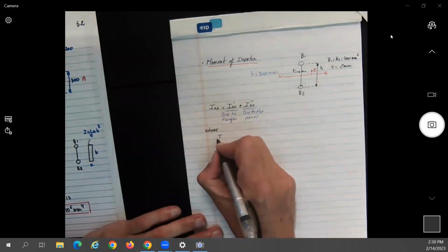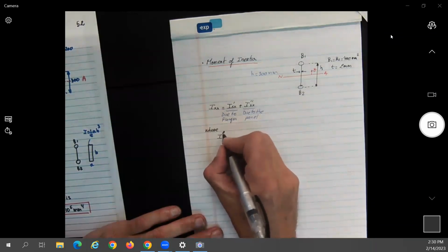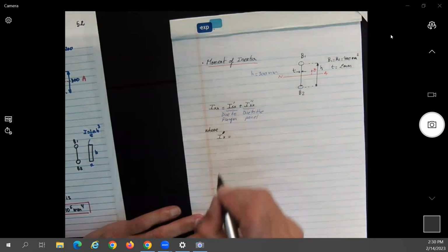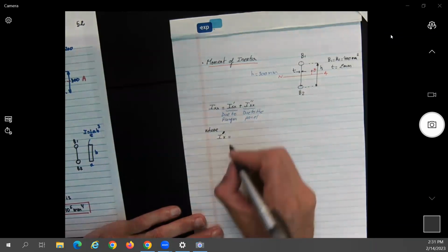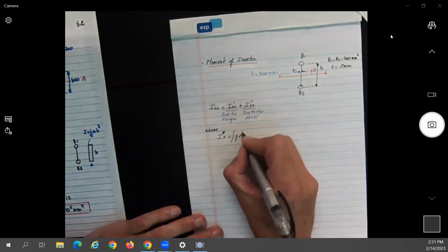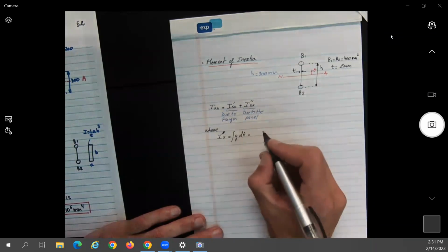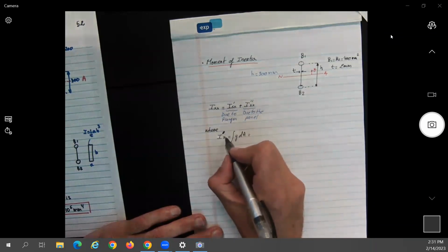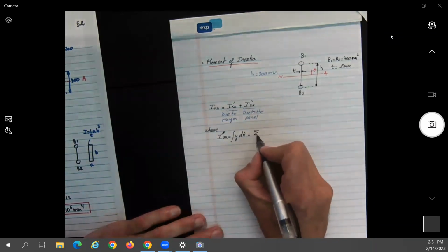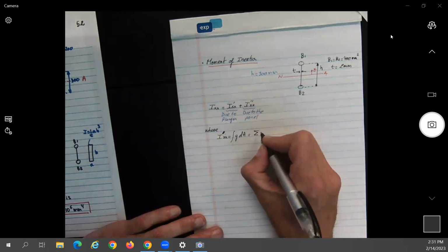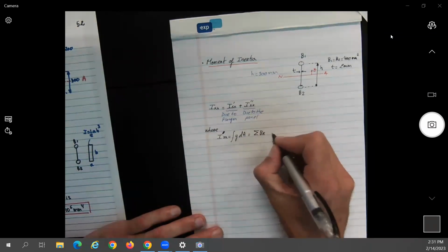So let's do first the one of the panel. Oops, first the one of the flanges. This is just one. What should be equal to the moment of inertia? Generally it is equal to what? The integral of y squared dA. So Ixx prime. But we say that this can be approximated by the summation of the B sub r's